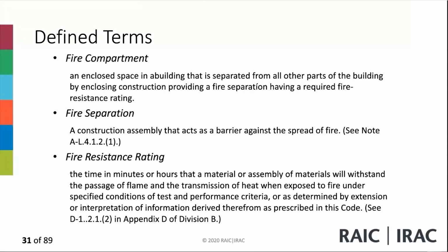You've got solid wood walls, floors, and roofs. And you've got protected steel columns under D2.8, and then we've got reinforced concrete columns and concrete beams, as well as D2.11. We've got glue laminated timber beams and columns. And in the new building code, we're going to have a whole new section related to the mass timber provisions. But for D211, we have it already in here. So this is for fire resistance.